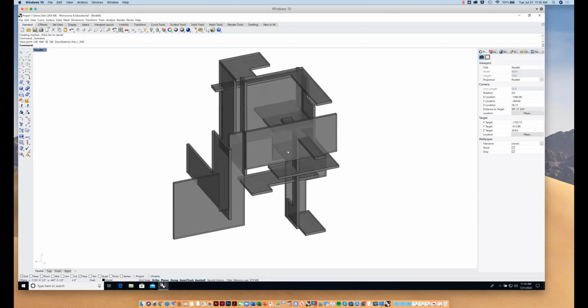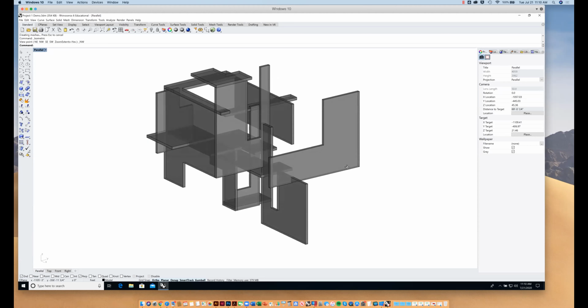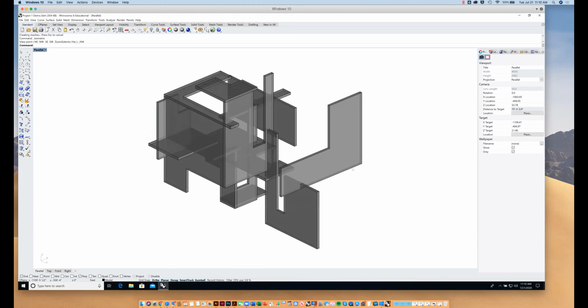This is my project 1. You guys each have your own project 1. And so there's a couple of things here. One is that you've taken these pieces that you had and you modeled them, you gave them thickness, like you were supposed to. And so we're going to think about those as one of 2 different materials in Revit. Some of these can be concrete, and some of them are going to be those aluminum panels, okay, that are basically broken down onto a 2 foot by 2 foot grid. And what's interesting is that we're going to add some surfaces in the Rhino model that, when brought into Revit along with the rest of this, we're going to apply curtain wall to, right? So we'll make those glass with mullions, okay?